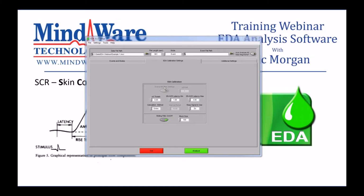If you were using a Bionex module like our impedance module and you're collecting EDA that way, then we would see this microsiemens per volt filled in, and that's going to be equal to the gain that you used to acquire your data, because we want to divide that gain out and get back to the raw microsiemens.